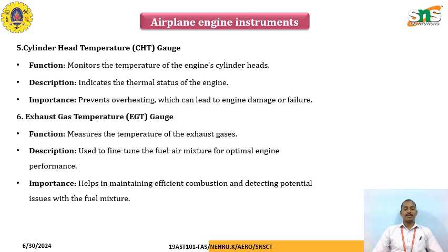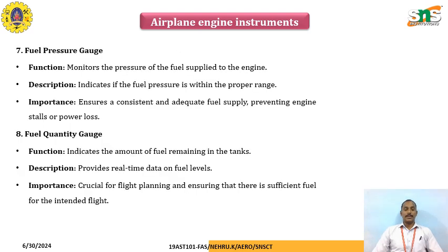Measurement here is very critical due to the very high temperature and high velocity. The exhaust gas temperature is used to fine tune the fuel air mixture for optimal engine performance. It helps to maintain efficient combustion and detect potential issues within the fuel mixture.